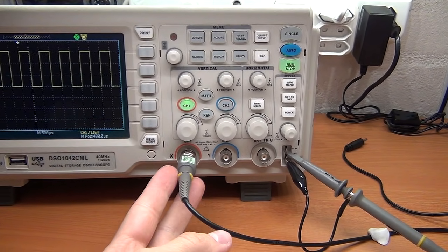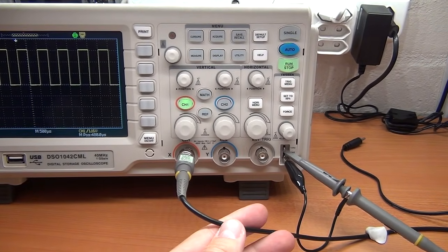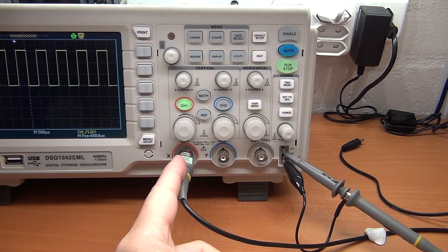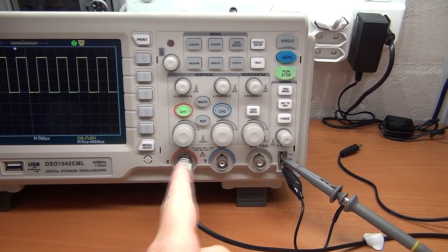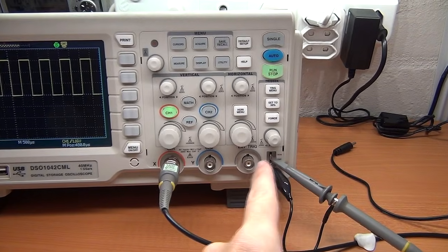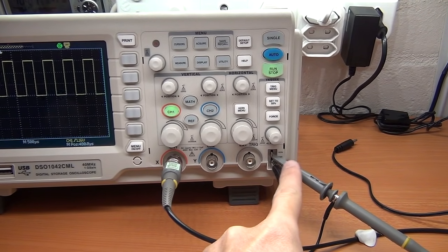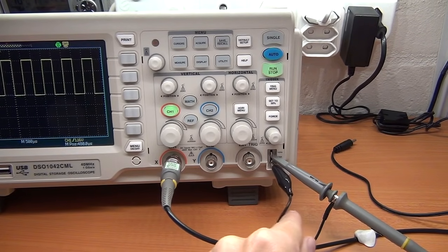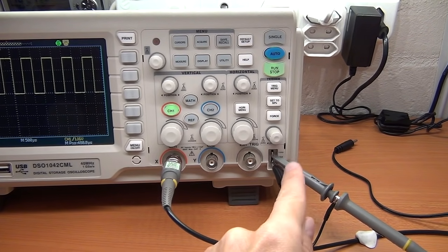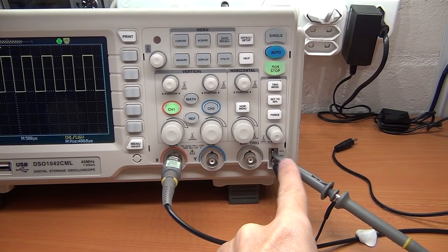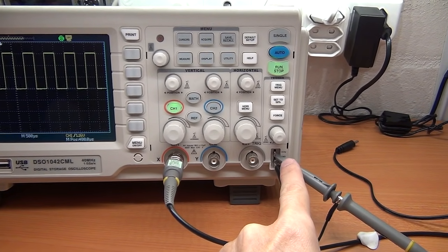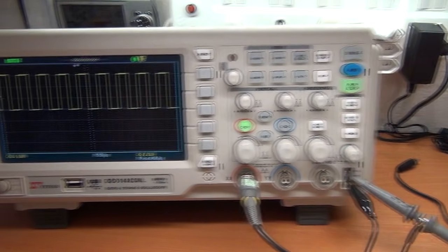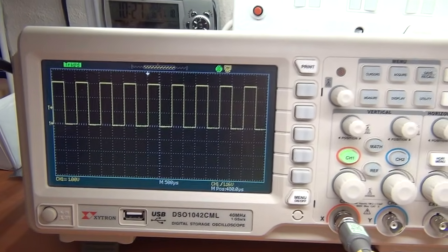But your oscilloscope probe is where you're going to pick up your signal. And this oscilloscope happens to have 2 channels. I'm just using 1 channel, which means we can actually view 2 signals at the same time. Your probe is what you'd connect onto the signal you're measuring. And then you have another lead, which is in essence the ground lead for the signal. So I've got these connected to a reference signal, which you can use to calibrate your probes with, but it makes a nice easy sample signal on the actual scope itself.